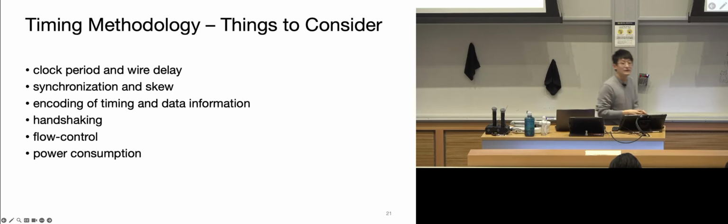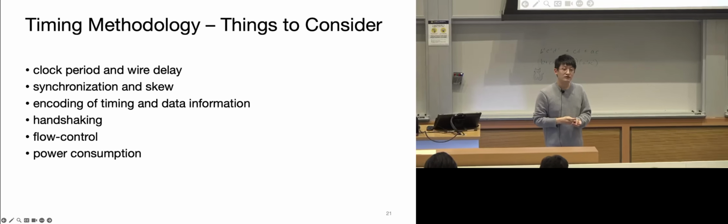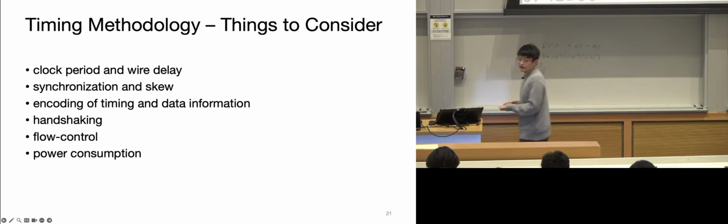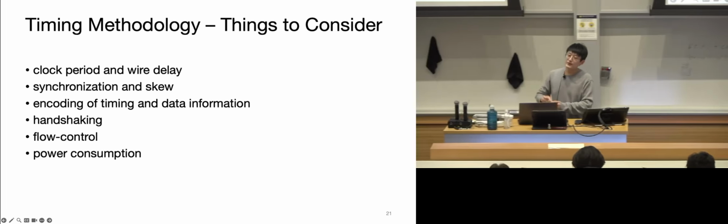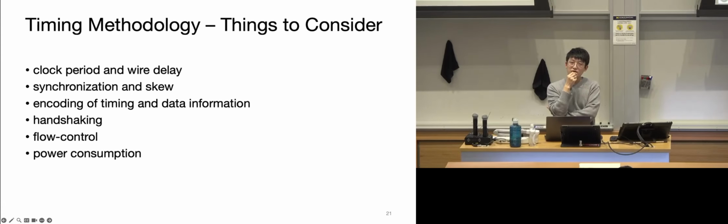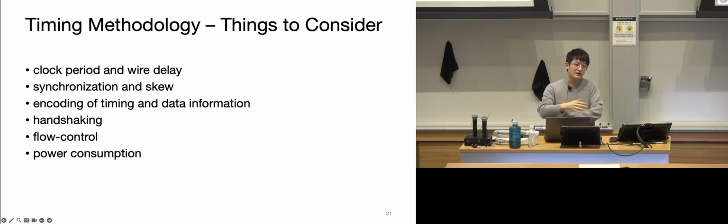Yeah. How does skew occur on a synchronous bus? How does skew occur on the synchronized bus? It will be if the distance is very long for the clock. Normally, if it's a reasonable distance, that should not be too much of a concern. So is skew basically one clock ends up behind the other just because of propagation delay?